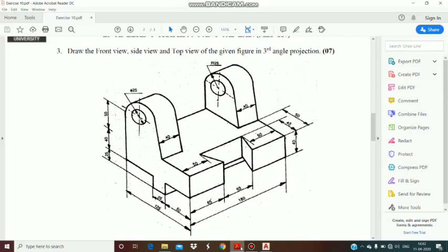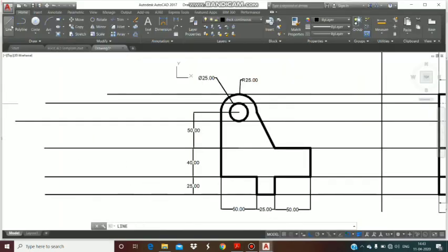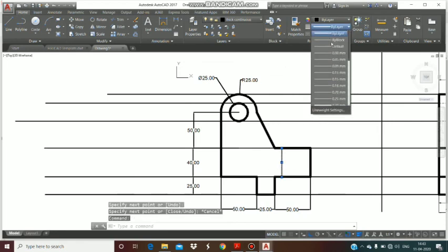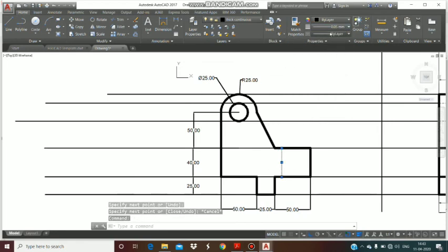If you want to show a hidden line, a line exists here at the distance of 40, you can also show that hidden line at the distance of 40 from this end downward. This should be thin and hidden. Distance of 40, thin and hidden too. Okay, our figure is complete. This is the left hand side view, and you can make it thin.